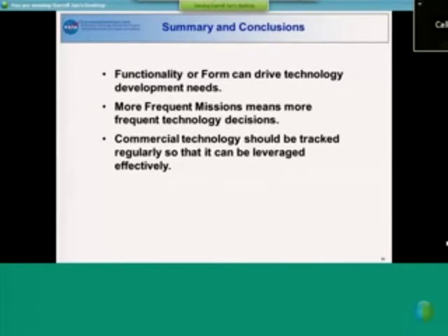It looks like compartmentalization in a spacecraft is a big advantage. In other words, the more compartments you have, the more opportunity you have, if there is a problem, that you can shut off one of the compartments. That is true. On the other hand, it probably costs you some money to compartmentalize. So there's probably an optimal point. Every time you compartmentalize, you'll have to have doors and feed-throughs and all that.